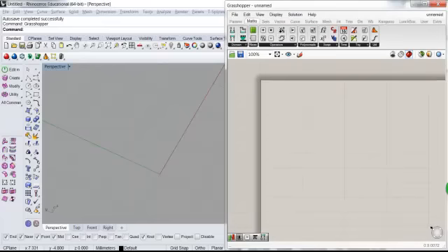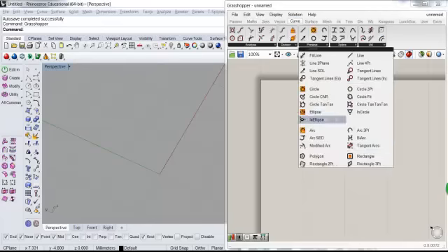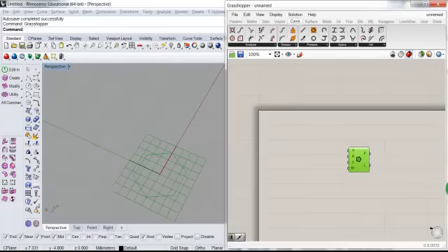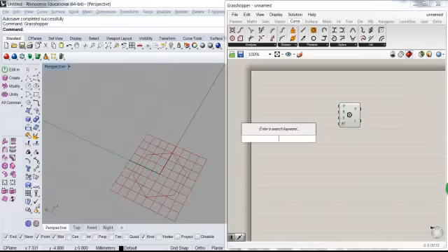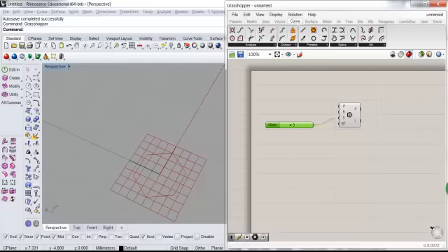So as I said, the first step is the extrusion. But we do not really do extrusion in Grasshopper. What we do is give a basic curve, move it vertically to different levels, and loft them. So what is the basic geometry? I believe you already know the answer. We need a triangle. We go to polygon and give the number of sides 3.